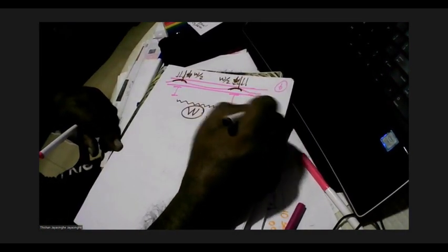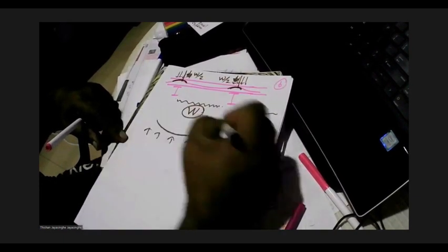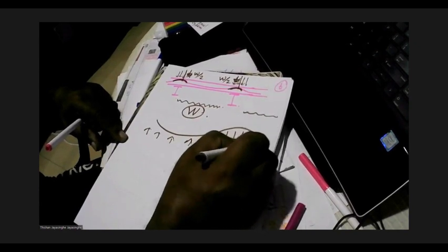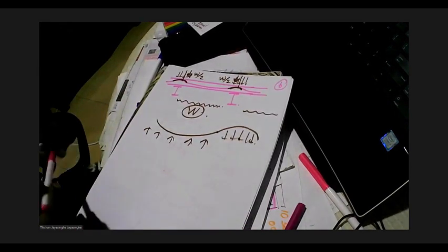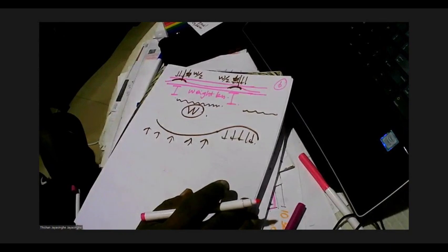So basically, whatever the load that we apply up, we apply downwards over this curve, because when we have a curve this way, the forces are acting upwards. When you put it in the other direction, forces are acting downwards. So this way, this will act as a weightless system, because pre-stress will look after the self-weight.